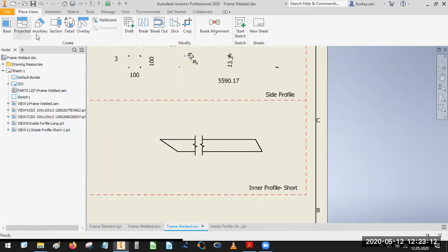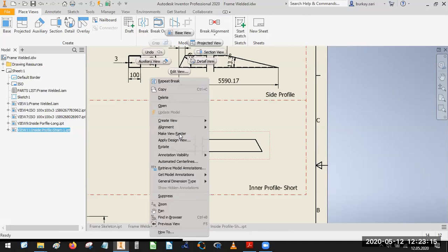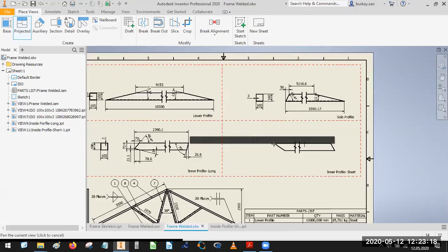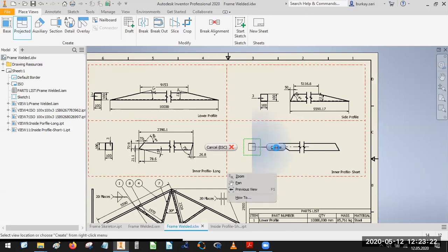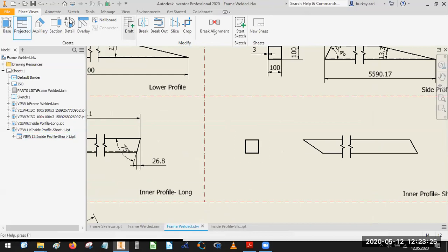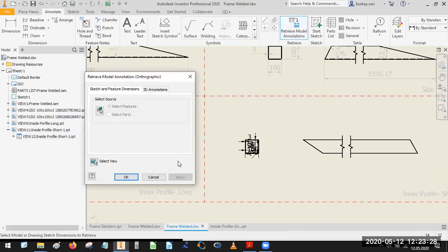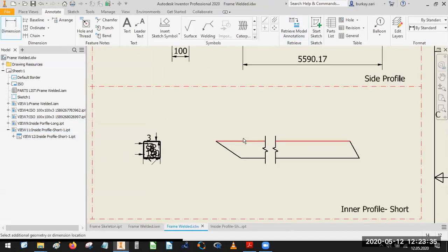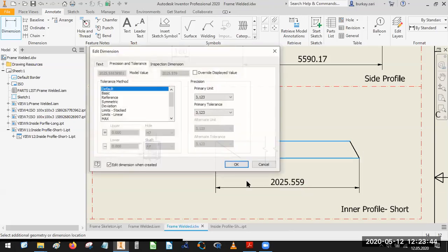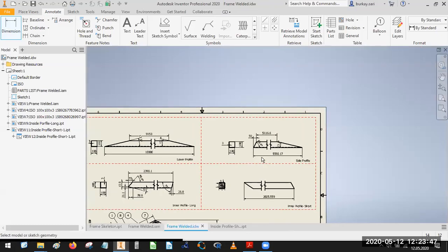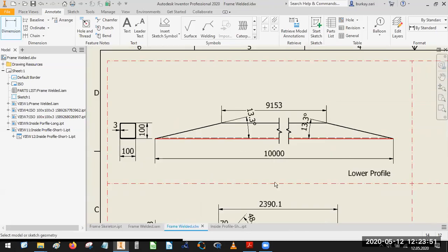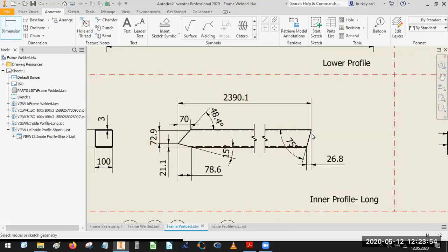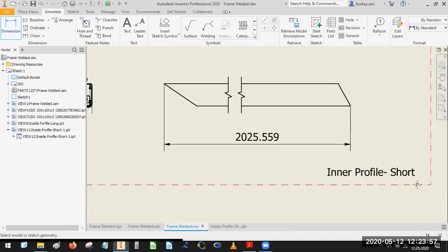Profile something like this. With selection, right click with the projection view. I need a side view from the right side. Again, annotate with this tool. Then the other things to be dimensioned. First of all, this time I need an end-to-end point profile because the material will be missing when I use that dimensions. Also, this is the longest length of our profile. Also, this one I need.